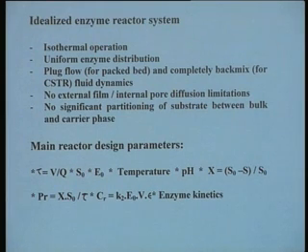We are not considering, that means even a fluidized bed is not considered as an idealized reactor system. So we are considering the two extreme conditions, either a plug flow behavior or a completely back mix system. Then we are also ignoring external film or internal pore diffusion limitations, if any. We are considering that there are no diffusional limitations, that means the rate of reaction is much slower than the rate of diffusion, which is fast enough. Then the last assumption is that there is no significant partitioning of substrate between the bulk and the carrier phase.